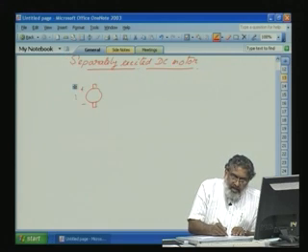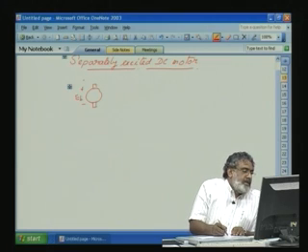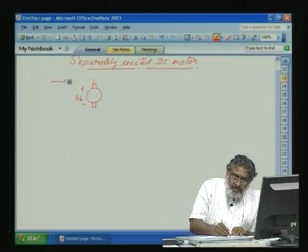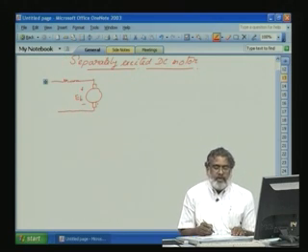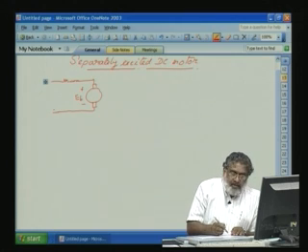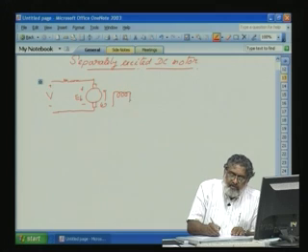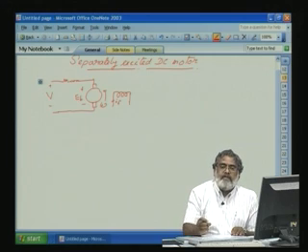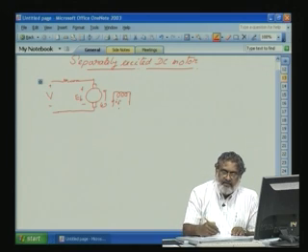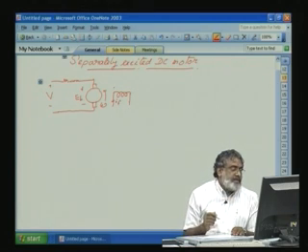Here you will have the back EMF EB, then the motor armature resistance and inductance here, and this is the applied voltage V, then the speed of rotation, and here the field winding. The field winding will be excited with the rated field current. So we will use a separate rectifier, rectifying the mains with a diode rectifier according to the rated voltage, and give it to the field. So the field will be excited.